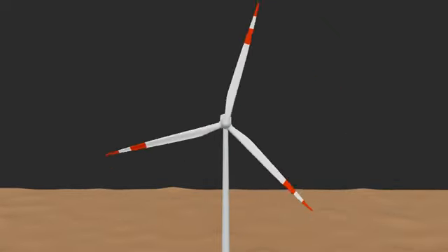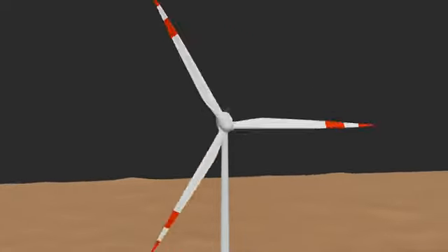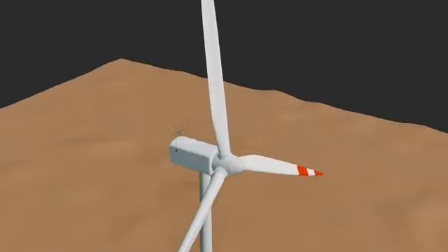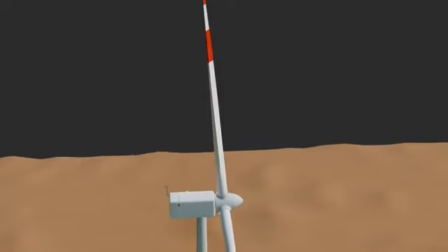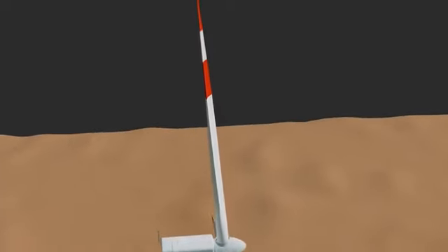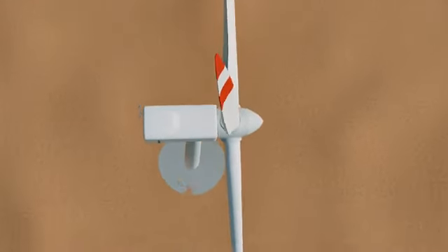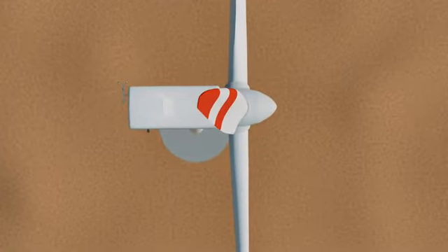Blade tips move faster through the air than sections near the hub. Wind hits different sections at different angles. Therefore, the blade is twisted, typically 10 to 20 degrees from root to tip, to maintain an optimal pitch angle along its entire length. This twist improves efficiency and prevents the blade from stalling.